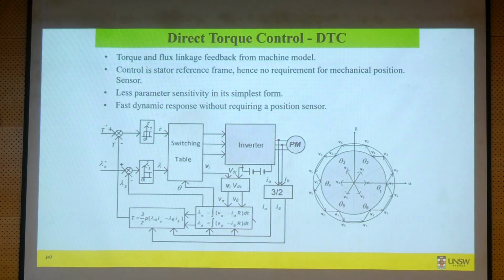the main difference between DTC and FOC is that in FOC you have the speed controller and then you have the current. So you are controlling current, even though you want a certain torque. Your main purpose is to get a certain torque, right? So you are controlling current, so you are indirectly controlling the torque. Whereas in direct torque control, your command could be a torque. You could have a speed controller here, and the output of that speed controller will be torque.